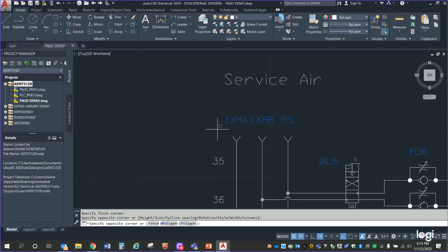Or you could take 125 PSI and reduce it down to 20 PSI. So we could do lots of things. You know, we also have filters and separators, and what do filters and separators do? Get rid of oil and the dust. Yeah, so we can get rid of oil, we can get rid of water, we can get rid of dust, moisture, rust, anything. Why is it important for the air to be clean and free of all those other things? So it doesn't come up the cylinders.